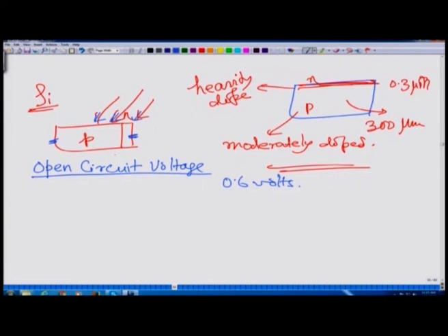So, that is the maximum voltage, but if you connect this solar cell to a circuit and you draw some current, the current will go this way, right, because this side is positive, this side is negative, this is my N side, this is my P side. When current is driven, your voltage might change, as it happens with any battery.